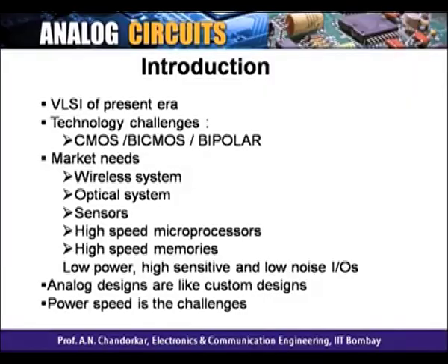The problem came because the technology earlier was bipolar transistors, and it is very ideal for analog performance. In fact, if you really want an analog chip to work better, you actually go for bipolar. There are two reasons we did not do that, though some companies still market it. For example, National's op-amp 741 is still on bipolar. Not all of them, but some of them.